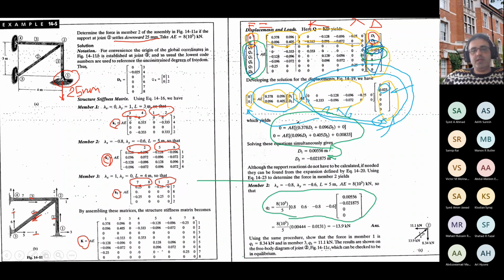However, the procedure that we were following in the truss structures will stay the same: defining the coordinate system, numbering joints, numbering elements, numbering degrees of freedom, then assembling the individual stiffness matrix for different elements, then putting all of those individual stiffness matrices together to get the bigger matrix for the whole structure, then applying the boundary conditions to come up with a smaller stiffness matrix for the structure with only the unknown deformations.